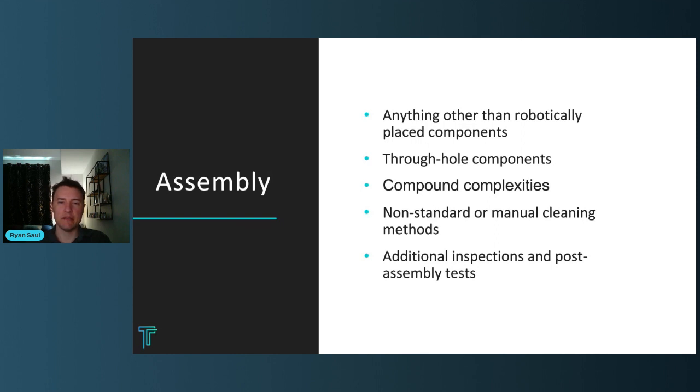I would say that press fit is another example of a technology that has good applications, but should be avoided unless you need it. Anytime you have press fit, you're going to have the evil dragon of NRE rear its ugly head, and so that means that there's going to be a die that's required to press your component in. There's going to be press fit support fixtures that are going to be required to safely press into your board.